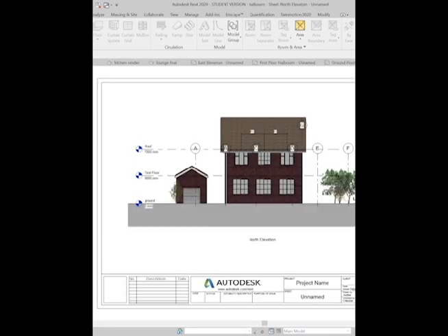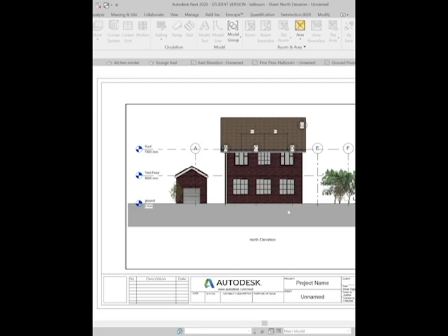We've got the front elevation, which, as I say, at a glance, apart from the kitchen furniture that's snuck on, which for some random reason is outside, looks a realistic build until you look at the measurements. So the first floor is at 3,600 millimeters. That's certainly over a meter too high.